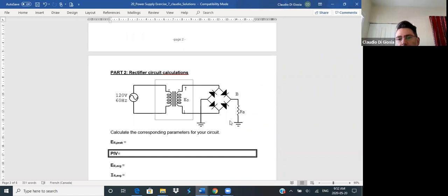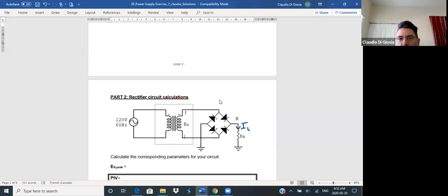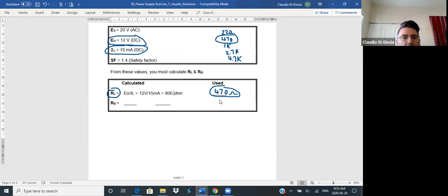Okay, so if you're looking for RB, this guy here, as I was telling Massimo before, this RB is basically to make your life a little simpler. Remove all of the other semiconductors, put the resistor value in with the amount of current that you need, the given amount of current. It's basically to decide how much current and voltage is going through these diodes to choose the proper diode from our chart. So let's finish off with RB.